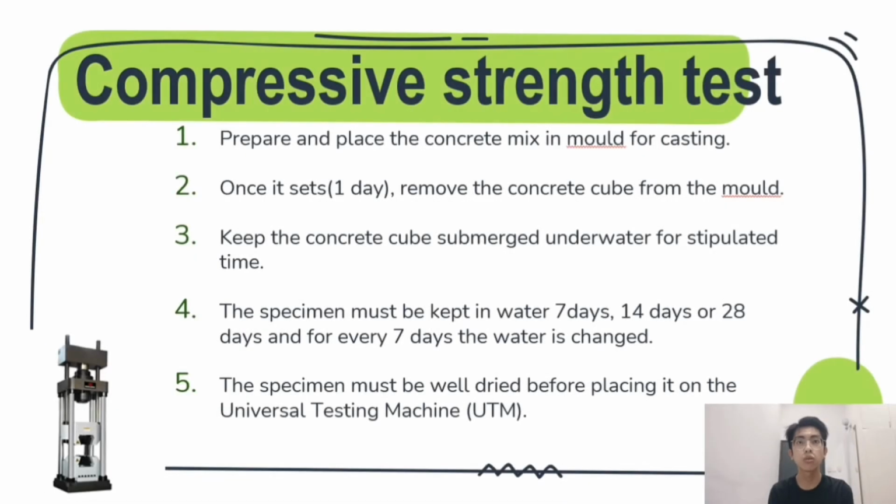So next we come to the standard test process. The first one we will be using is the compressive strength test. First, prepare and place the concrete mix in the mold for casting. Next, once it sets for 1 day, remove the concrete cubes from the mold.